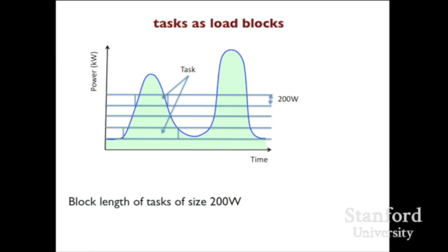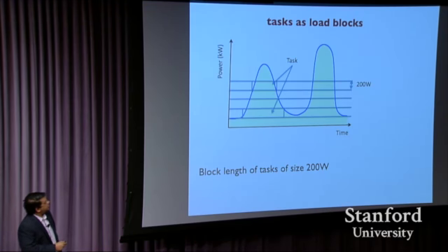So now let's go to the next type of flexibility. One question that came up when we started looking at this was that there are all these technologies looking into scheduling, right? Scheduling when you run your washing machine, scheduling your EV, or scheduling different forms of consumption. So we wanted to create a feature that allowed you to measure the potential for scheduling. Obviously, this potential may be smaller than what we show, but it's an upper bound. The idea is very simple. Take your daily consumption and break it up into chunks of 200 watts.